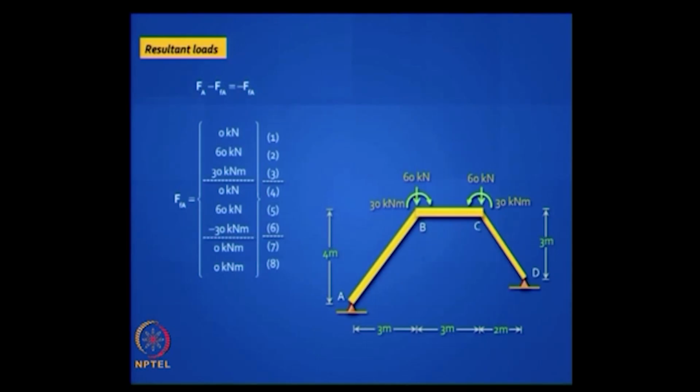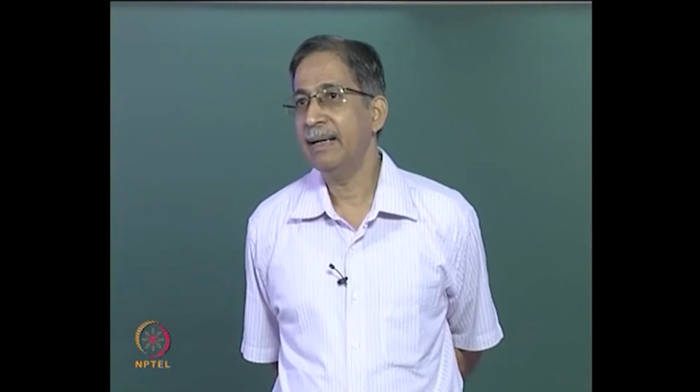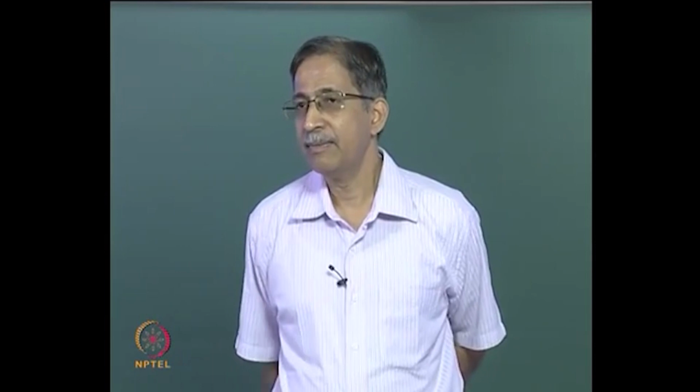What you are having here will give you exactly the same active displacements, the same dA vector, the same deflections at B and C, vertical and horizontal, and the same rotations at B and C, okay, and at A and D, okay, because you have to superimpose these results with the results that you get in the primary structure when you have that UDL, okay.